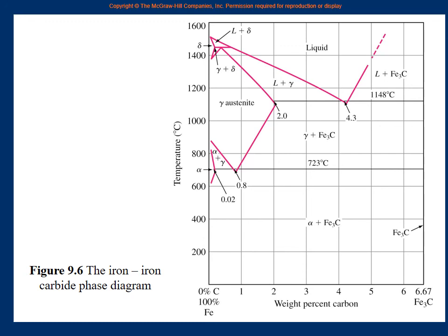But the main complication, or what is good for materials engineers, is the three solid phases of iron: alpha, gamma and delta. Because of them we have many phases here, and once we add carbon, carbon does not stay as a separate carbon, it makes a compound with iron called iron carbide or cementite. Therefore we have four solid phases here, alpha, delta and gamma for iron, and cementite, four solid and liquid. So there are a total of 5 phases including the liquid phase here.